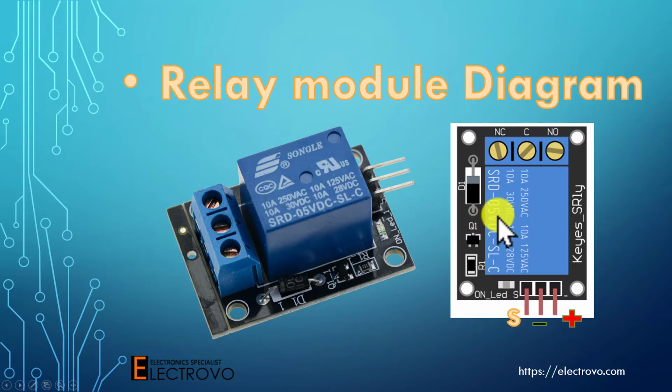So this relay is a 5-volt switch. It is activated by 5 volts, and it can carry voltage up to 250 volts, 10 amps. These are the three pins for connection: normally closed, common, and normally open. And this is the power for the relay. Because it's 5 volt, you need to connect 5 volts here. If you connect a lower voltage, it will not work. If you connect a higher voltage, you might burn this board and relay. And this is the signal input, so the signal comes from this.